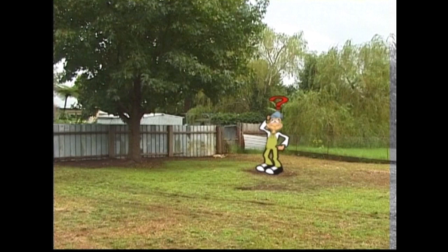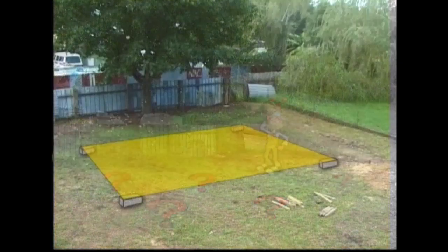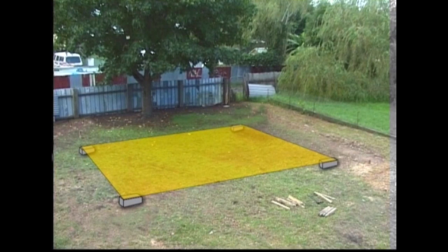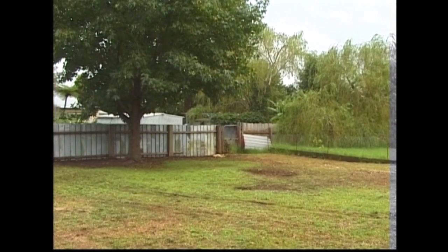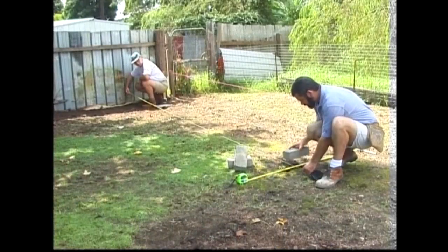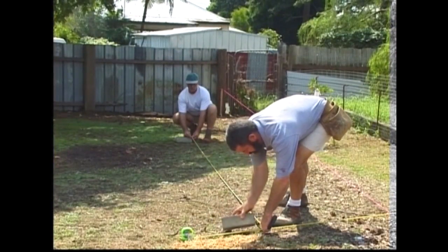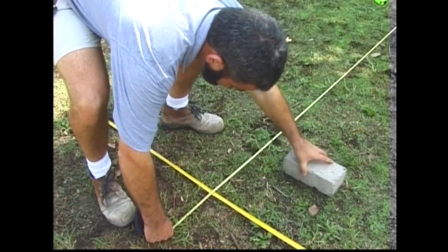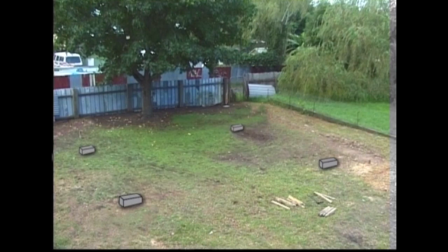On most sites, it is necessary to find the high point of the ground on which the structure will actually sit. Before this can be done, the approximate location of the building needs to be established. This can be done by inspection of the building block in conjunction with the site plan. A quick measurement gives the approximate location of the corners of the building. This gives an overall idea of the job.